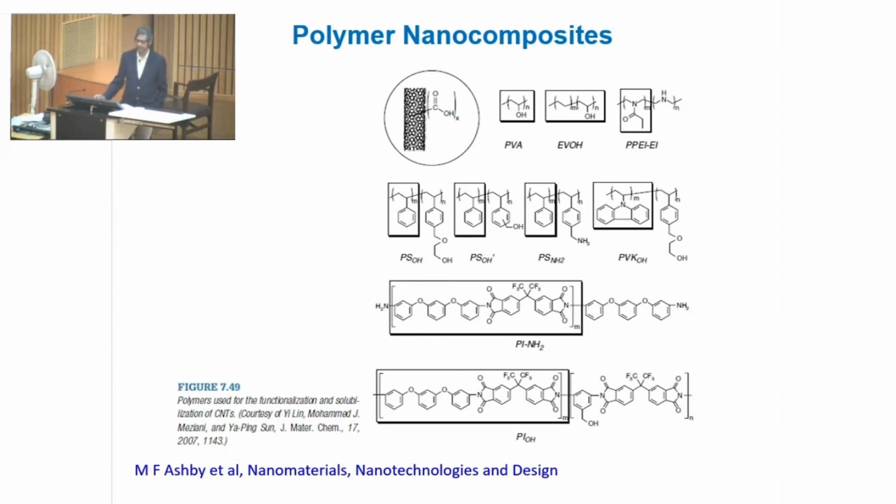Inclusion of CNTs in polymer matrix nanocomposites can also be used to improve the thermal conductivity of this nanocomposite. The CNTs create a percolation network in the nanocomposites to conduct the heat, with conductivity up to 3.5 times higher than what is observed in pristine polymers. However, the thermal conductivity of the nanocomposite is still far lower than the theoretical value, and this is something which is a big concern.